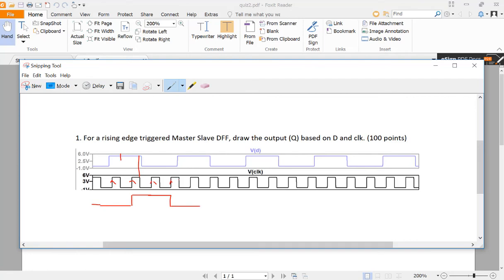Okay. Sample a 1, trigger a 1. So it actually changes here. So I'm wrong at this point. It's not correct. So actually it's going to trigger a change because this one is going to sample a 1. It's going to trigger a change here. And then sample a 1 again. Okay. So it's not going to change at this rising edge. It's going to keep that 1. And sample a 0, so that's why this rising edge is going to toggle this 1 and make it a 0. And sample a 0 here.